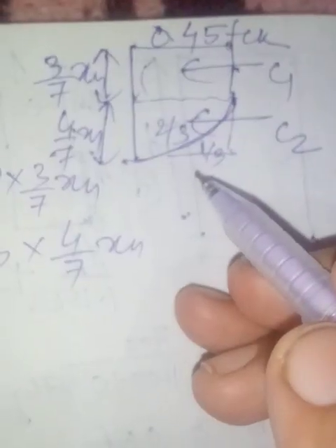For C2, same 0.45 fck, B into 4/7 of Xu is for rectangle, but this is not a rectangle. See, the lower part is 1/3 and the upper part, the parabola, is 2/3 of the rectangle, so it will be 2/3. This one is C2. If we add these two, we get the C value as 0.36 fck B Xu, and here we are going to find out